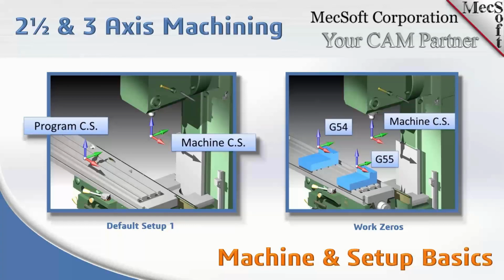You can move that origin, okay? Even in the standard, in the early configuration, you can move that origin by creating a work zero and putting that work zero underneath your setup one, and you can define where that work zero is, whether it's at the top of your stock, bottom of your stock, however you want to locate that work zero, and then that work zero will then become the coordinate origin for all tool paths.